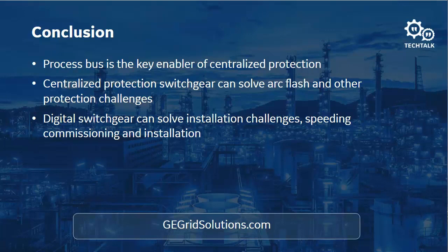I hope I addressed this question during my presentation, because I hope that I very explicitly explained that the UR relay itself can be the master clock for the process bus network. If it is the master clock for the process bus network, the merging unit does not need a separate GPS. So it would not need a separate GPS.